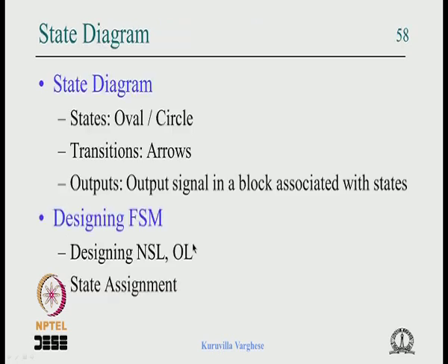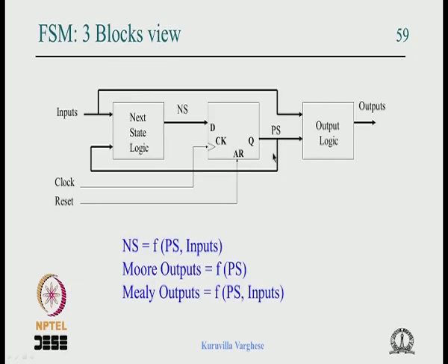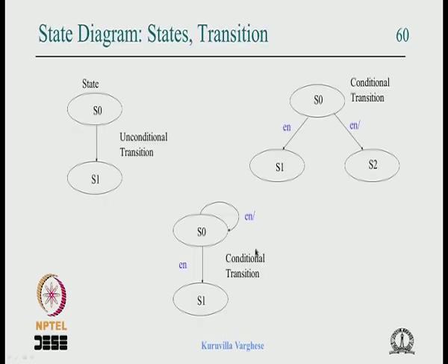So it means that the state was some state and it is waiting for some input to go high from the data path. The data path is doing something, and the state machine is waiting. However many clocks come, it can remain in that state for a day if that input does not come. So it just remains there in S0, and when that signal comes it transits to S1 and does something else. So that is what is shown here.